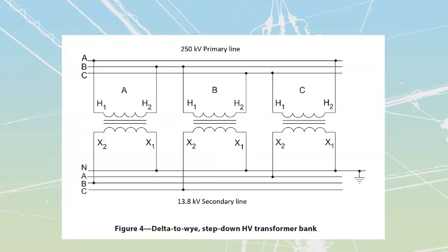We once again could do things poorly if we go through a reverse over here. If I come in as a high voltage delta over here, I'm going to lose those benefits of having a lower phase voltage. I'm going to have windings that are going to be good for 250 kV. That's a lot. And then flowing out over here on my secondary line, well, it's not necessarily going to be terrible. Depends whether we need a neutral or not on that one. But I am going to have all of my current, whatever I run out of the transformer on my lines, going to have to come through my phases themselves.